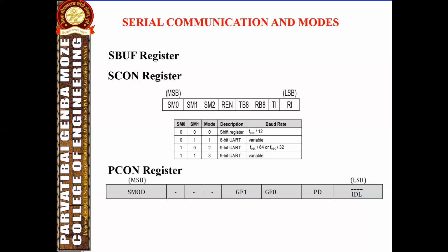Those are called mark. The ASCII character, an 8-bit binary, is framed in between the start bit and a single stop bit. The LSB is sent out first. When there is no data transfer, the signal is high, which is referred to as mark. The low is referred to as space.